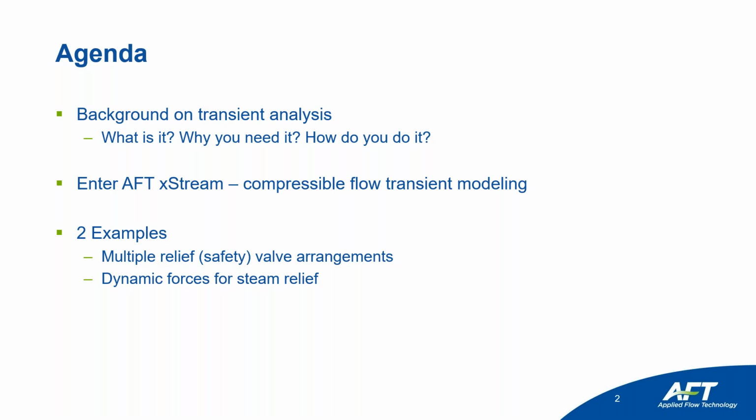there's a paragraph in ASME B31.1 in the Appendix II that talks about relief valves for power piping that, well, if you're going to have multiple relief valves in your system, make sure to check them out and maybe turn them in different directions so they don't interfere with one another and all that. But they don't really give you a whole lot of guidance on how to do that. They just say to do it. So that one was really what I wanted to focus on, because I thought that was pretty funny.